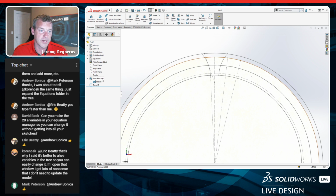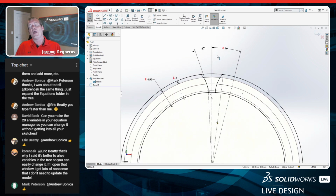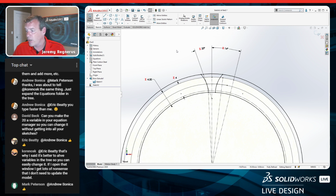Okay, so now we're going to go back into this sketch. How do you add an equation if you've already typed the dimension in? This is a great question. We're going to double click on this, and all we have to do is update it and say that's going to equal. We're going to go into our global variables. There's our pressure angle. Boom. That was a great question from the comments. I love it. So now we have 3 values over here, and we're going to look at changing these all later on.